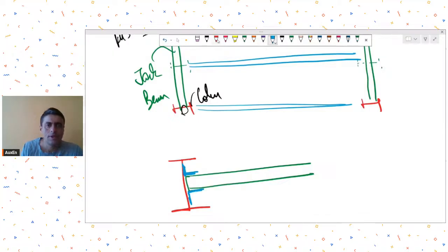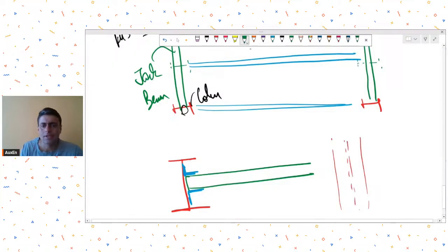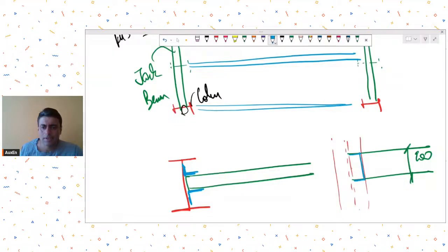In sectional view it will look something like this, and let's say this is my RHS 900. So you will provide web cleats like this, one at the front, one at the back, and you could have through holes and provide through bolts over here.